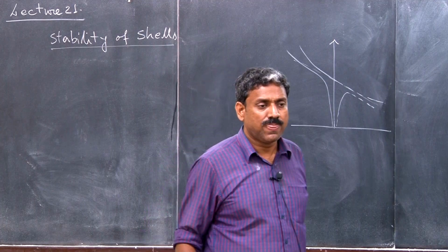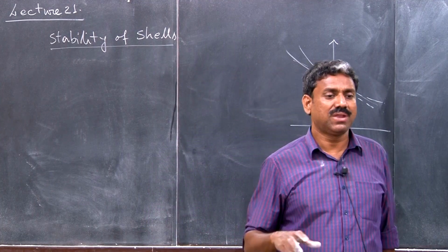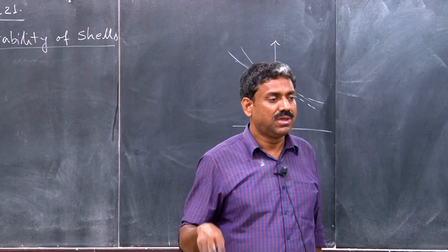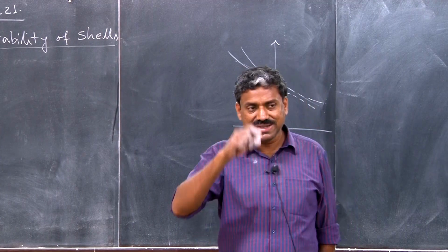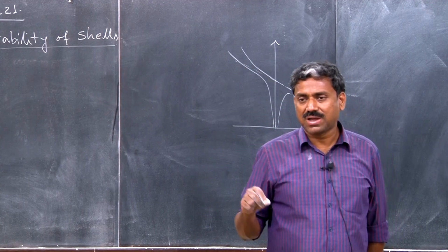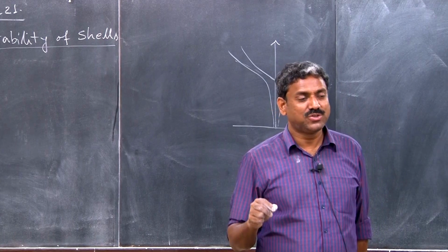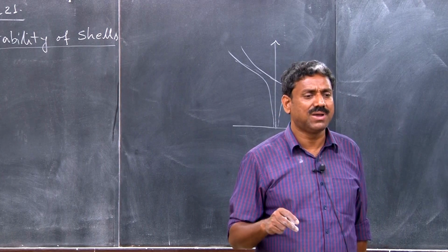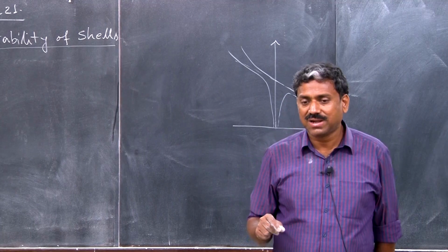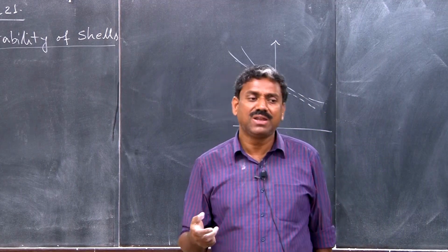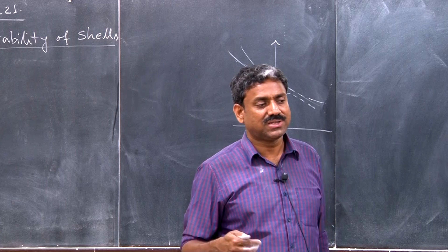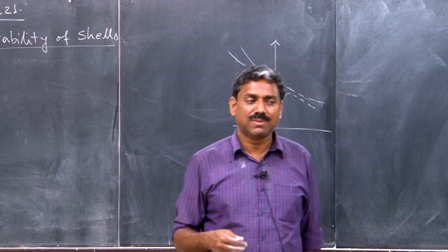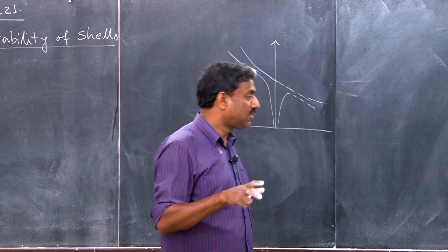So, if you take a cylindrical shell, or a spherical shell, or a conical shell, and test it, you will see that the critical load obtained through experiment is much below the theoretical critical load obtained through linear rigid analysis. That was not explained until later. It was explained by a group of researchers.